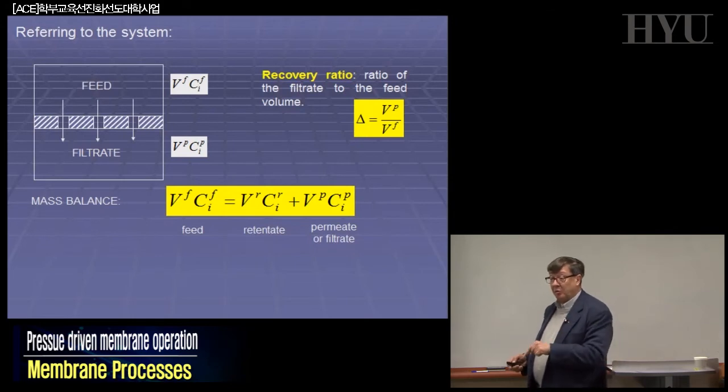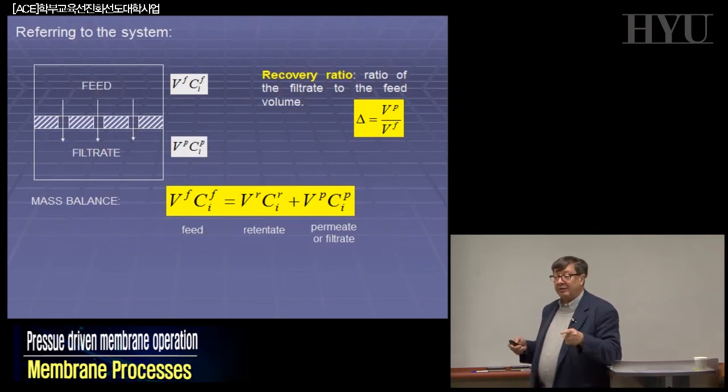However, we are working today for having recovery factor 90, 93, 95%. That means if you have 100 cubic meters, there will be 95 cubic meters of fresh water and only 5 cubic meters back to the sea. These 5 cubic meters are the concentrated one, what is called brine. And these are a big problem today. One of the big problems in desalination, we mentioned already in the introduction, is brine disposal. What to do with all the concentrate?